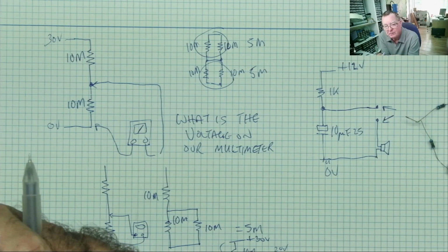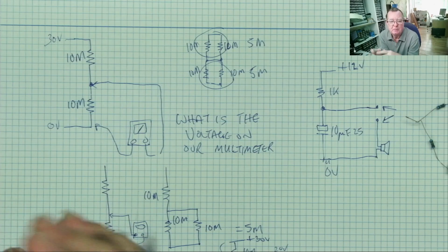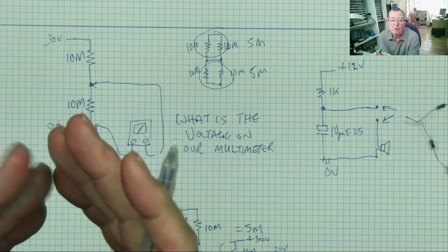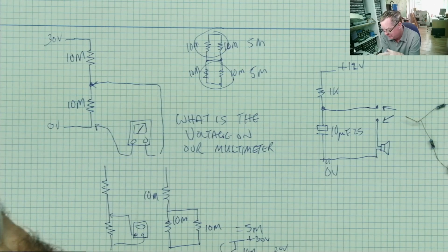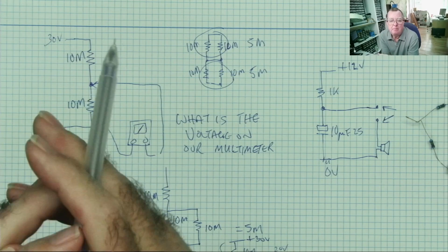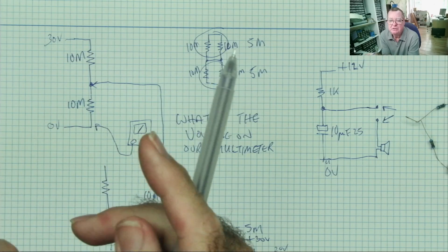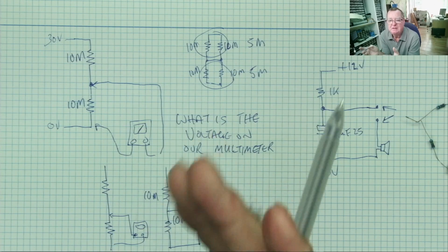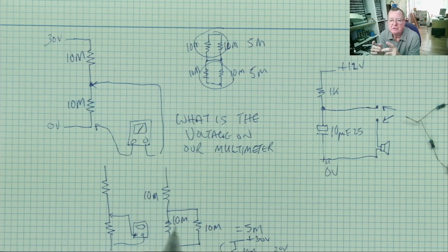So what have we learned? Well, we've learned this can be a little bit devious with questions sometimes. We've learned that Ohm's law really does always apply, even when it looks like it doesn't. And we've learned that our multimeter, in some instances, can actually affect the voltage you're reading just by reading the voltage. And this occurs when there's a very high resistance in the circuit. So I hope you got that one right. If you didn't, or even if you did, I hope you enjoyed the explanation of it. Now let's have a look at question number 2.